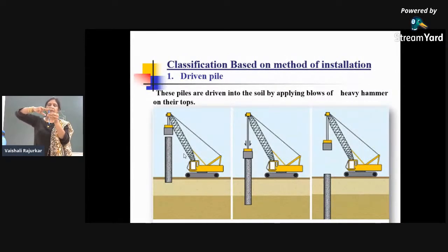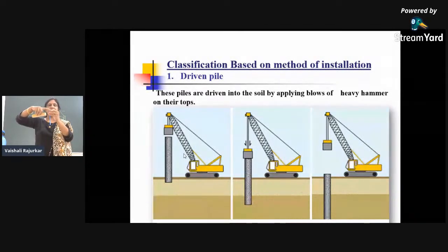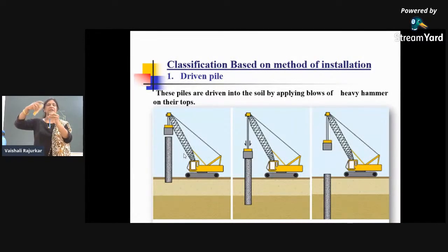Here, in between the hammer and the pipe top, the cushion is placed. Here you can see this. My finger is just similar to the cushion, and then the hammering is done. While hammering, due to this cushion or the dolly or helmet placed above the pipe, the top of the pipe does not get damaged during the driving operation, right?